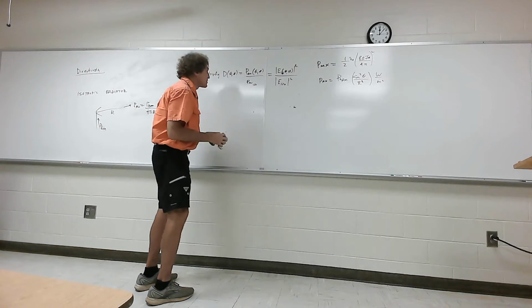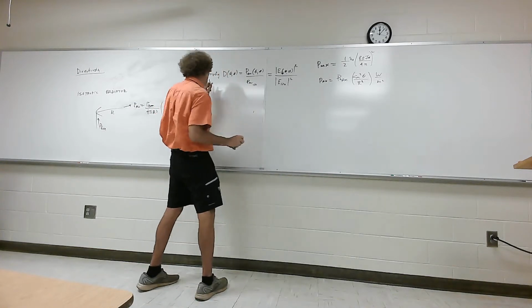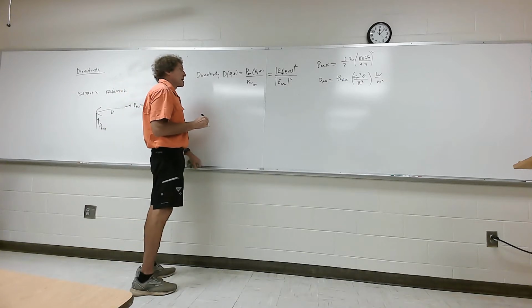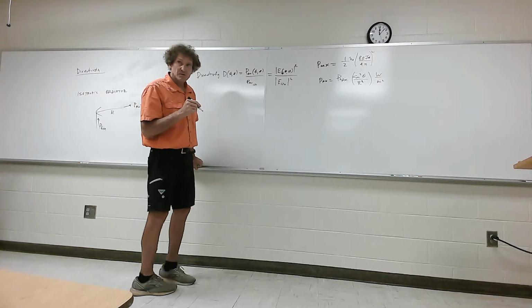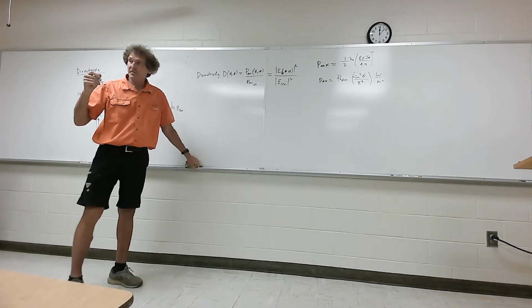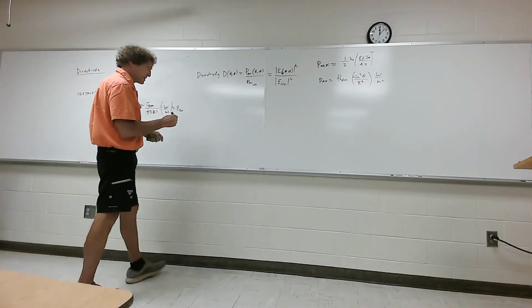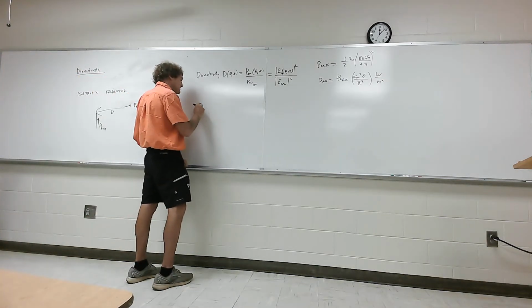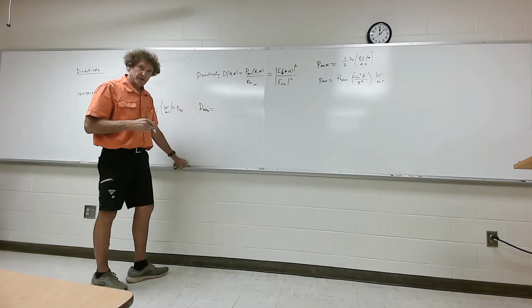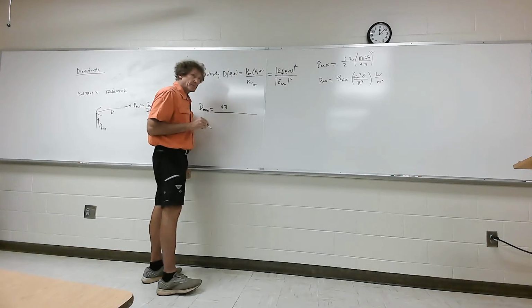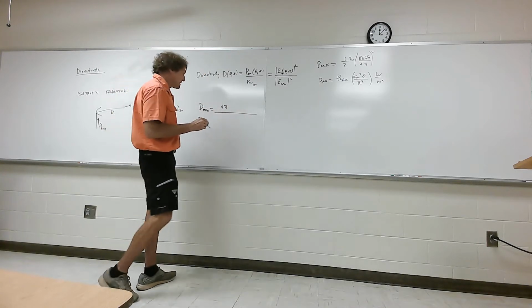Now, the way we calculate this directivity: the directivity itself is a function of angle, but it has a maximum value. First, I'm going to tell you how to calculate the maximum value, and I'm going to work backwards on it. I want to give you what's used, and then I'll tell you why it's used. So the maximum directivity, D max, where D is the symbol for directivity, is simply given as 4 pi divided by the beam solid angle.